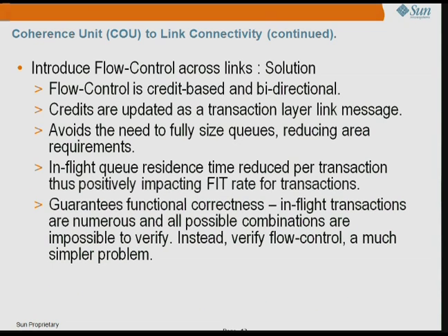Our solution is to introduce flow control across the coherence links. Sender and receiver both have credits. The sender has a credit amount, and the receiver releases the credits back to it over a transactional link message. This avoids the need to fully size queues, reducing area requirements.